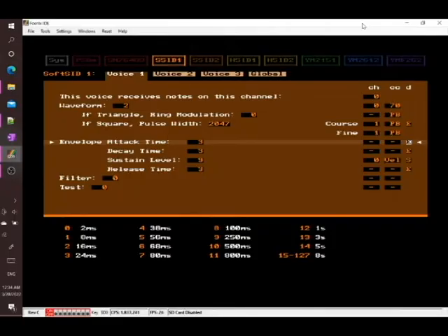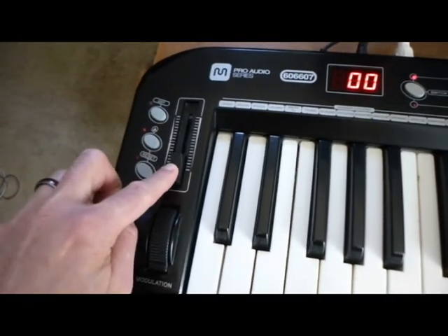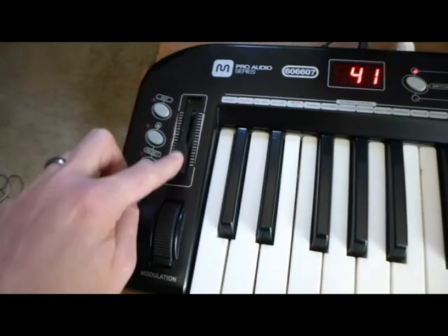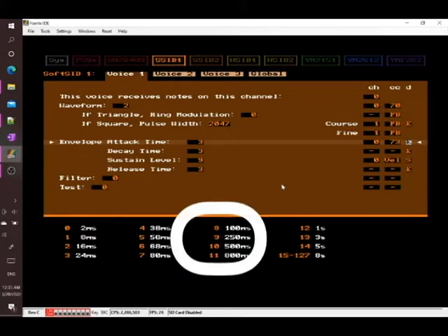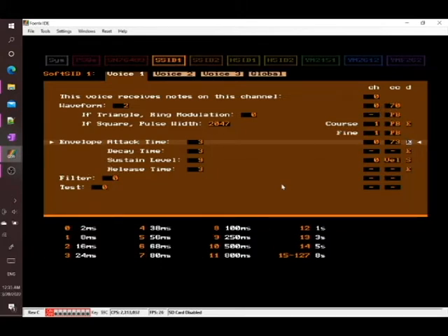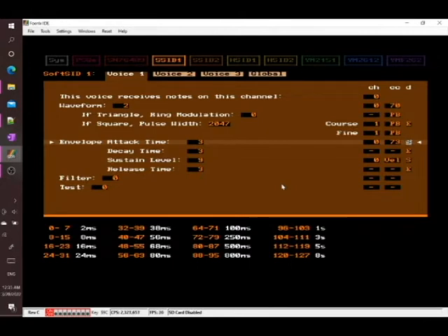To solve this, I can use the software to set this parameter to spread mode by hitting the Enter key here in the distribution column. This spreads the 16 values out evenly over the entire 0 through 127 range of the slider. Even the on-screen help area updates to reflect this. In exact mode, only a 9 will result in 250 milliseconds, while in spread mode, any controller input value between 72 and 79 results in 250 milliseconds.